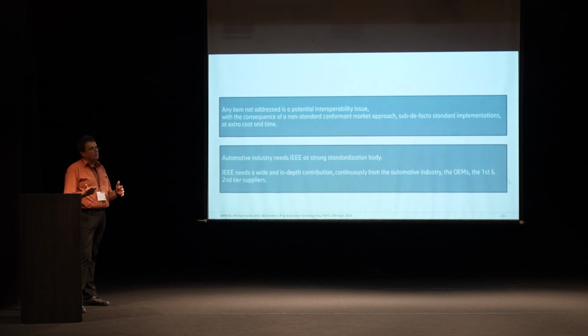And the other topic is the low power mode itself. It has some regular meaning. With regular signals, we have seen some EMC emission topics, for example FlexRay, where you see the FSS and potentially it does not come from the communication. Even, we've learned, it might not be a topic of the communication, it might come from the power supply.